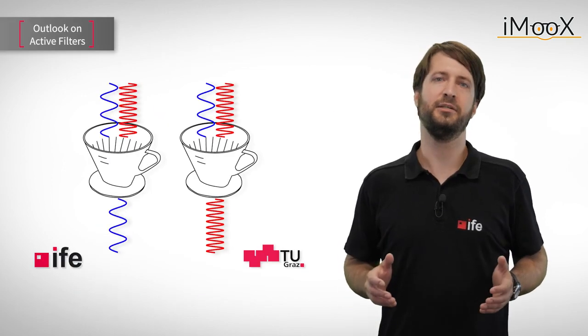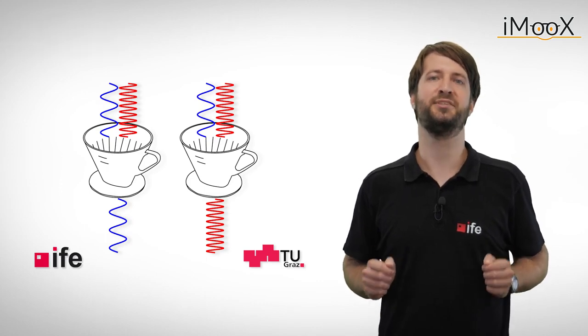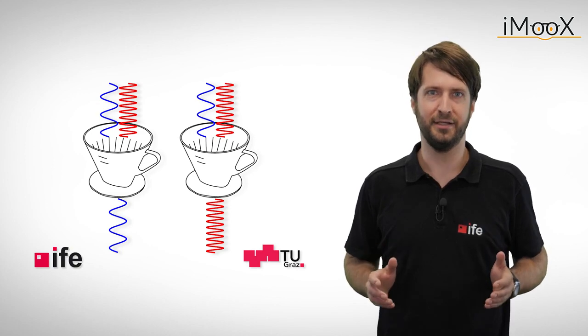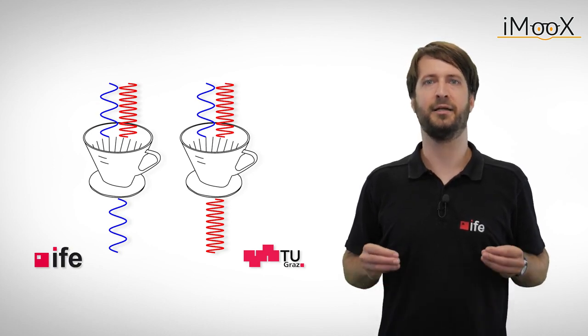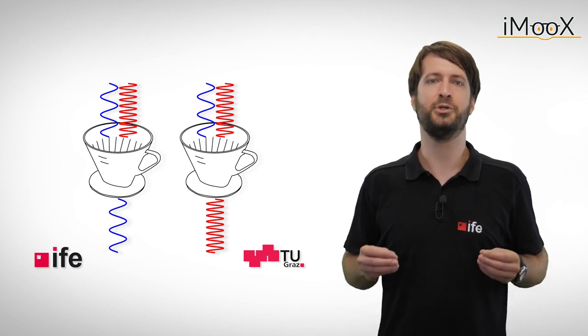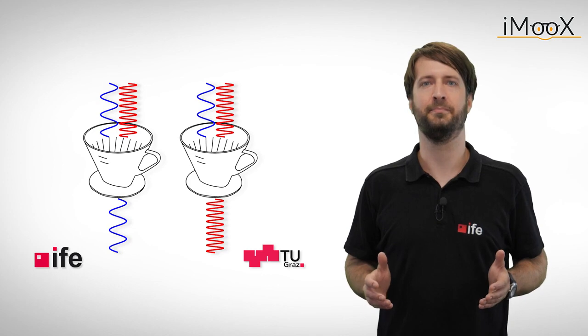If you have seen our videos about amplifier circuits, you can now try to build such an AM receiver by yourself. All you need is a long wire for the antenna and some basic elements, like an adjustable capacitor, an inductor, a diode, some resistors, and either a transistor or operational amplifier.